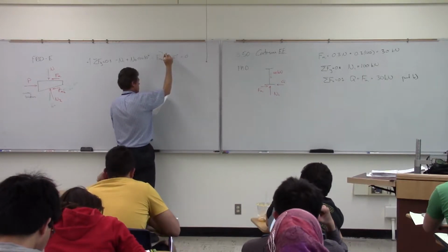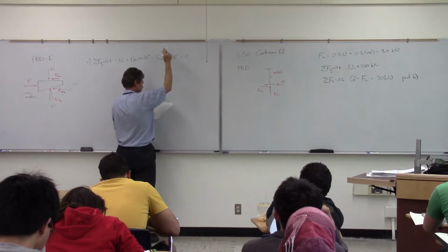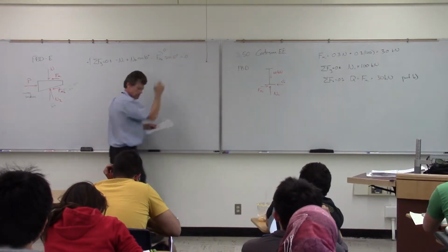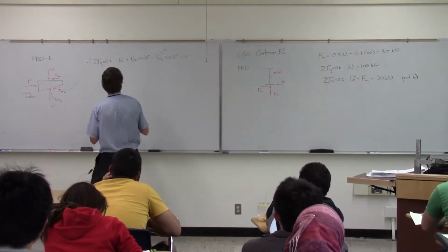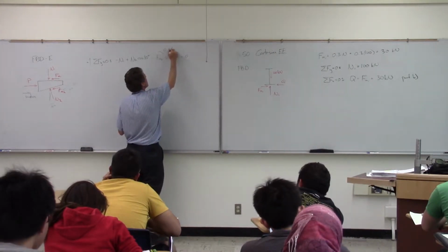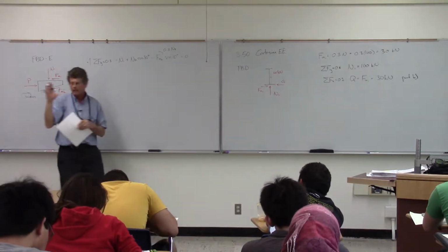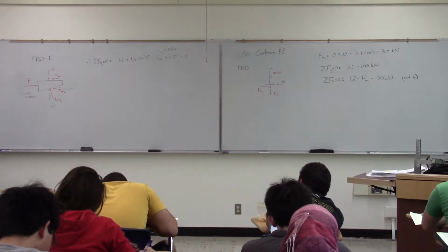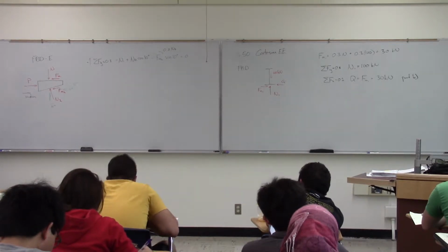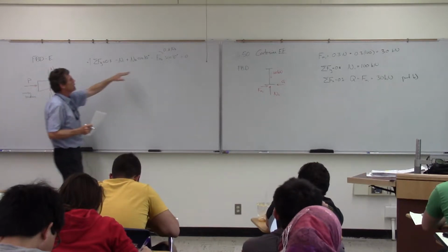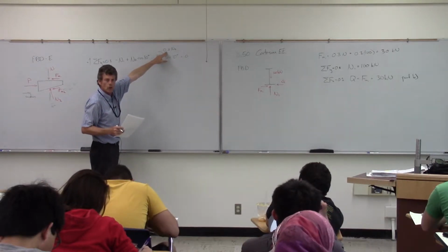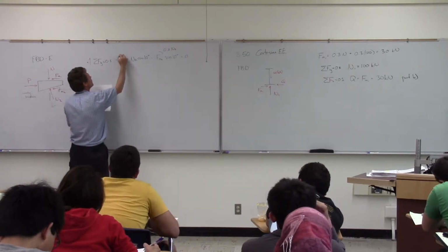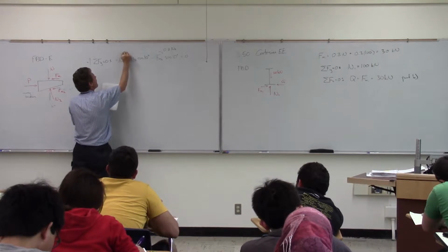Now one thing we'll note, we can substitute in, what was it? 0.3? Yeah. Again, that's the nice thing about breaking it up into that vertical and parallel and perpendicular components is then we can describe that parallel in terms of the friction coefficient there. So basically now we have this equation down in terms of one unknown because we just solved for this one.